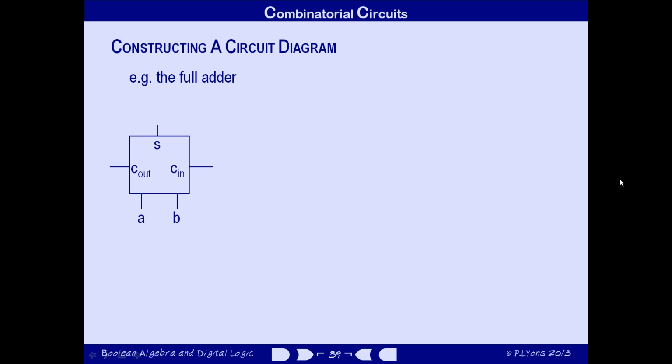Now, there's a similar but simpler circuit that resembles this called a half adder that doesn't handle carry inputs and carry outputs. Although it's often taught in digital logic courses, it isn't a great deal of use for doing realistic arithmetic, so we've jumped straight to the full adder circuit that can actually do something useful. And just for the moment, we'll also jump over the step of designing the internal circuitry of the full adder and assume that it already exists.